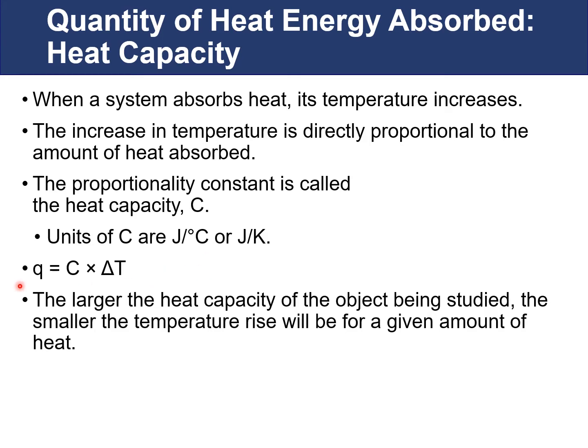The general equation is the amount of thermal energy transferred, or the heat energy, Q, is equal to the heat capacity times the change in temperature. So we can look at this in a bunch of different ways. One could be how much heat is needed to raise the temperature of a particular object by 2 degrees Celsius. So you're specifying the change in temperature, you're talking about the object and identifying its heat capacity, and trying to figure out how much heat you need to apply.